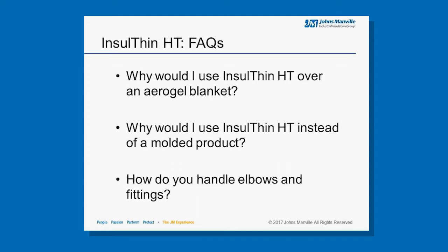So why would you use InsulThin HT instead of a molded product? The primary reason is clearance or installation efficiency. Clearance with respect to space constraints and installation efficiency with respect to larger diameter pipes, vessels, and equipment. We typically get the question of how we handle elbows and fittings.